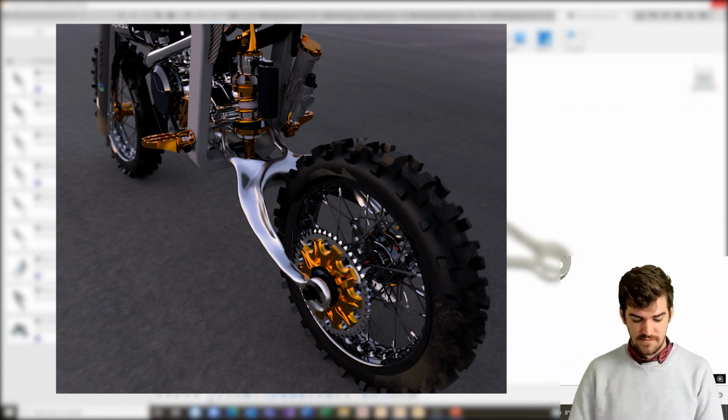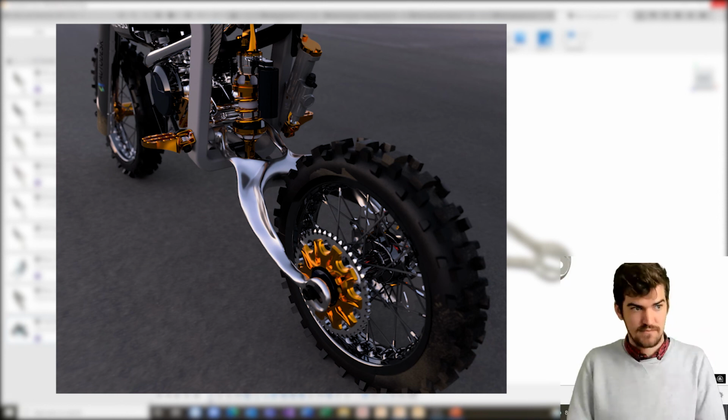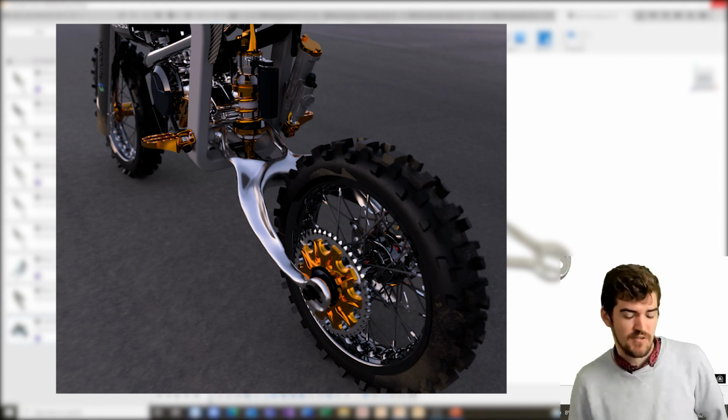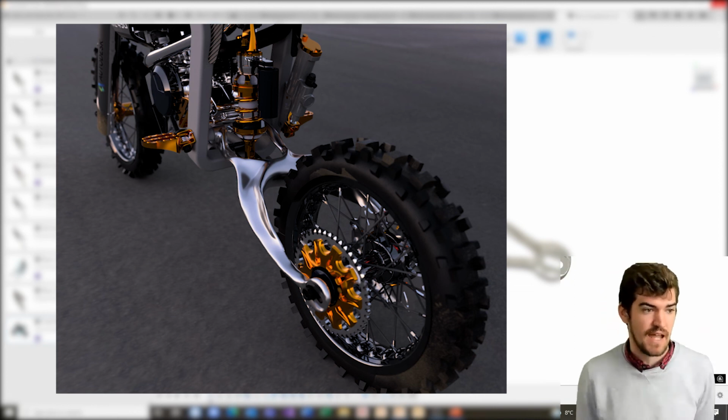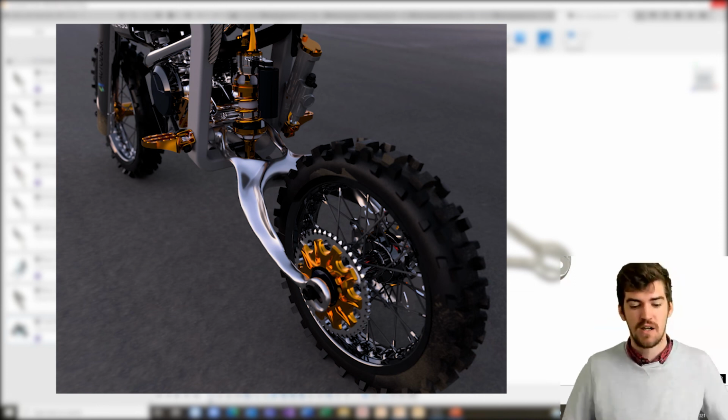During your presentation, you were editing the part and essentially adding new geometry for both the preserve and obstructive. Can you reuse geometry that already exists? For example, when you added the tire, could you have just brought the tire in from the assembly and said that is obstructive geometry? Yeah, you very much can. Any geometry that's in the model itself can be used as part of the study itself. It can just be assigned as either preserve or obstructive geometry.